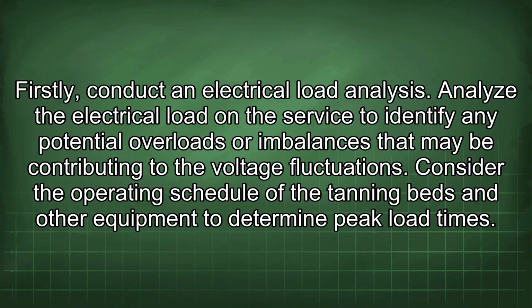Firstly, conduct an electrical load analysis. Analyze the electrical load in the service to identify any potential overloads or imbalances that may be contributing to the voltage fluctuations. Consider the operating schedule of the tanning beds and other equipment to determine peak load times.